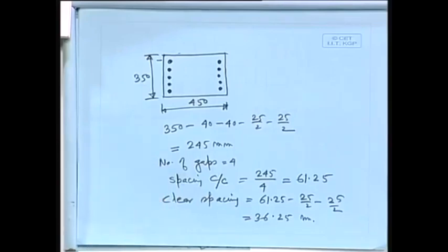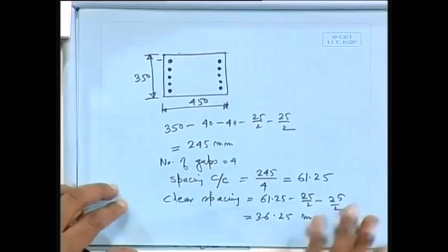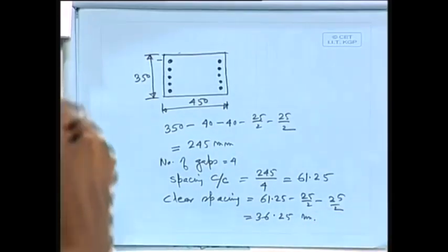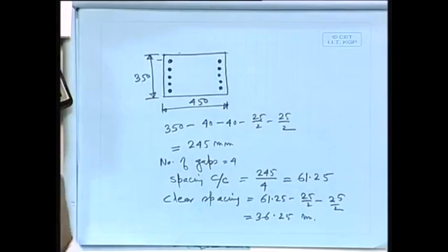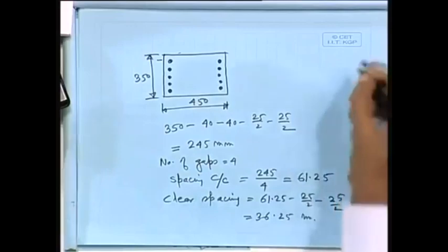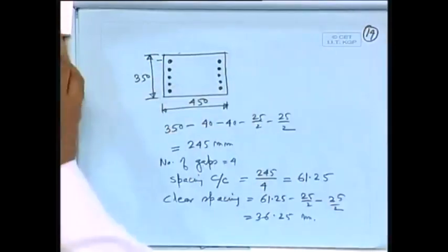So we have enough gap, because we have to provide that so the concrete does not segregate. That's why it is very, very important in your reinforced concrete design that your clear spacing, all those things, that is detailing, that we have to specify. Okay. So let us conclude at least this particular class today. We shall continue in the next class. Okay. So thank you.